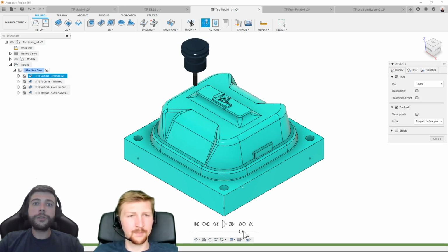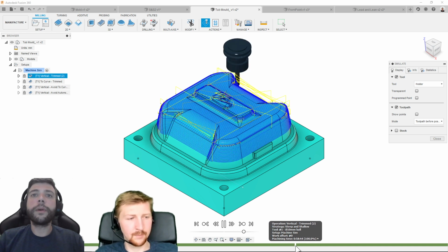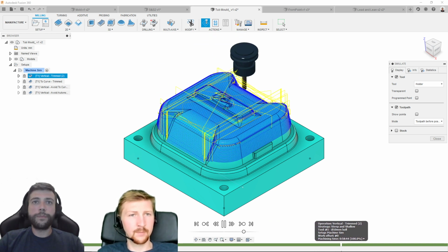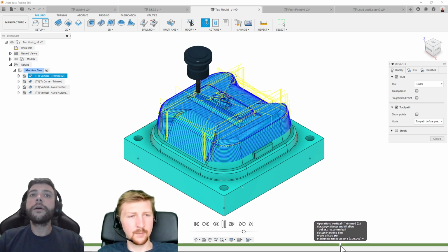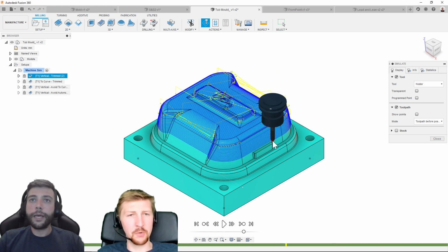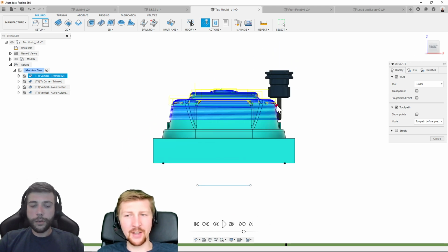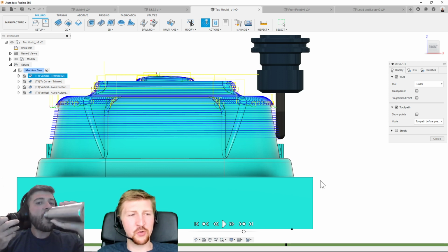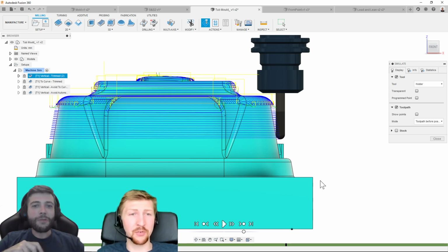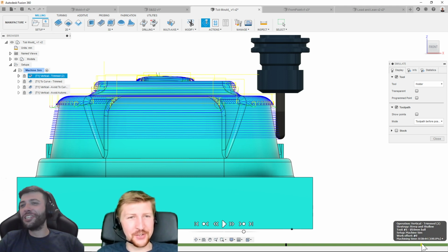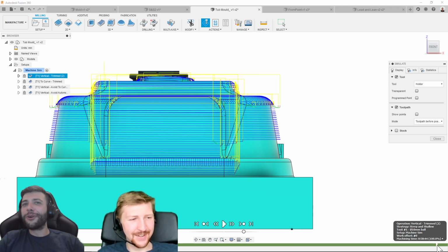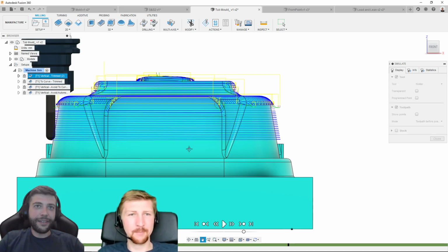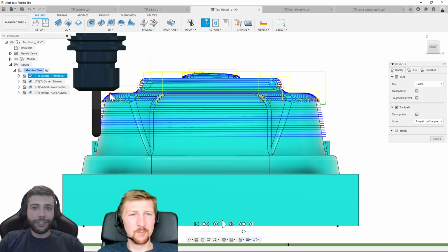Let's take a look at the simulation and bring it round about to where it stops machining just one side. I had so much hassle about a year ago. I was making a generative seat bracket for Martin Ashton, if anyone out there is a mountain biker, and I had to trim the toolpath so much with boundaries to stop this sort of collision from happening. But if we look exactly at what Richard is saying, one step down, we bash into the part. Maybe two step downs, let's say, because we go probably 1 millimeter, I've said here.